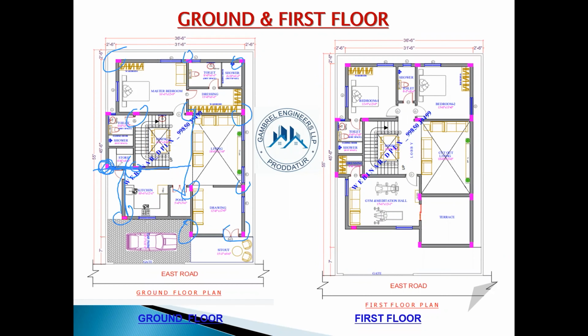Now this beam would be resting on this column, so the beam becomes more stiff, and upon this beam another beam is going to rest. This beam's resting point is nothing but a point load that we study in our academics. This actually acts like a point load on this beam. And even here, you'll have one more beam resting on this beam, and this beam is being rested on this point and this point. So keep a column here also. These are the basic concepts that we have to consider for fixing the columns.